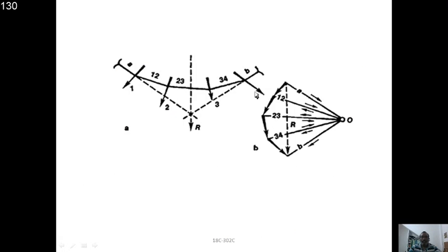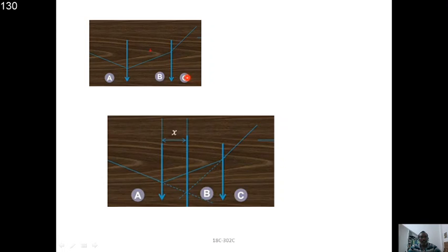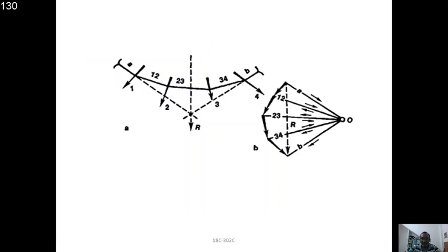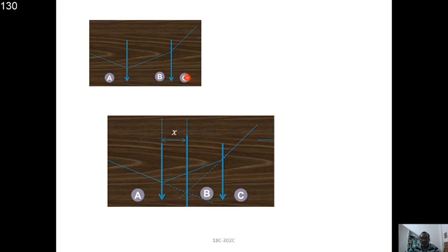So please see that. This is the shape. In this one, A1 at 1 to 10 scale, that is 300 mm divided by 10, is 30 mm. So this distance is 30 mm. And for B, this distance, we are taking 450, 400, divided by 10, therefore it will be 40 mm. So draw A, B, C, D like that, all the areas A1, A2, A3. And after that, they are to be added as collinear forces or collinear areas like this one.